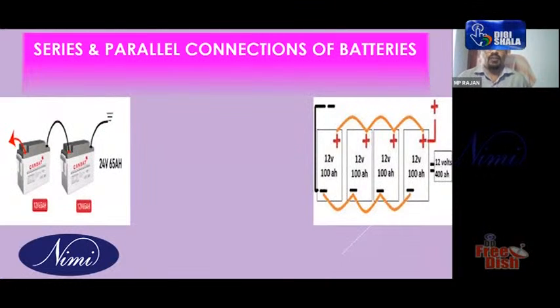Like solar cells and solar modules, you connect them in series, parallel, or series-parallel connection. It depends upon our requirement of power. In the same way, batteries also should be connected in series or parallel depending upon the requirement. Our inverter ratings will show on which input voltage your inverter is working, and on which voltage your charge controller is working.